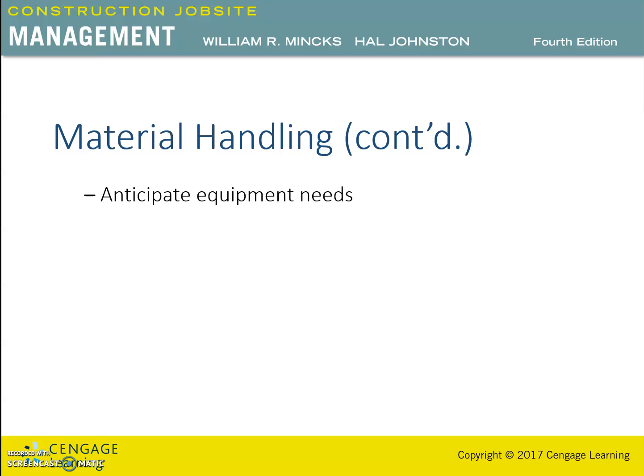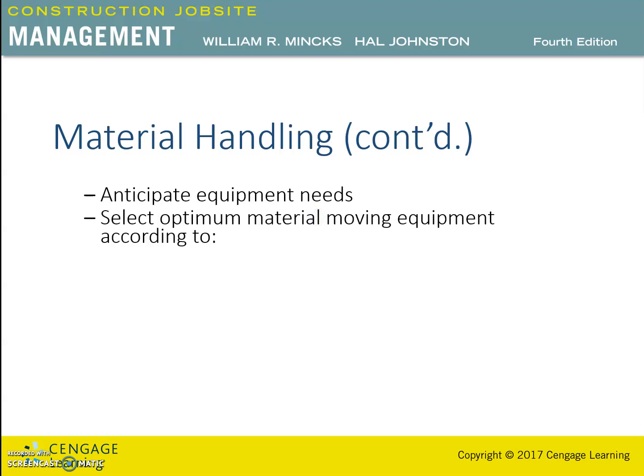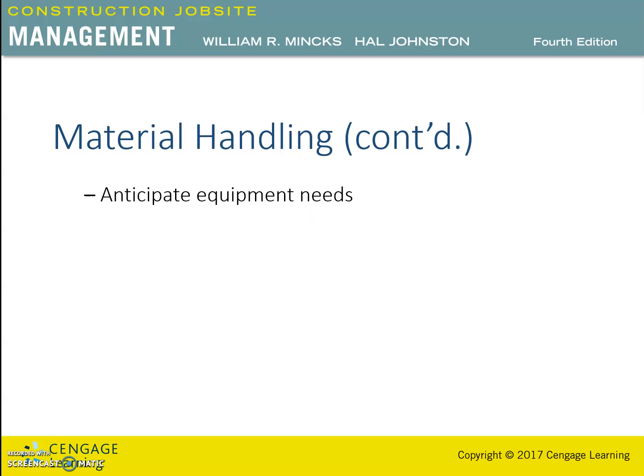Planning at the start of the project can provide adequate provisions for lifting equipment through the duration of the project. So permanent equipment should be selected for the majority of lifting and material handling. Some equipment needs may be temporary and require special machinery such as a mobile crane for a few hours or days because of the size, location, or amount of material delivered to the job site.